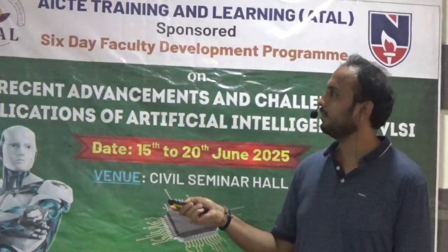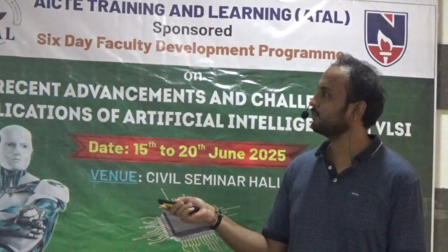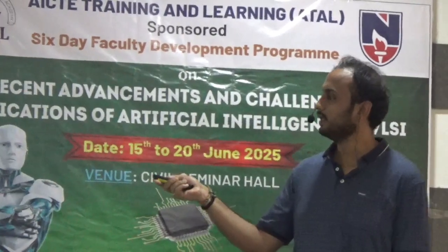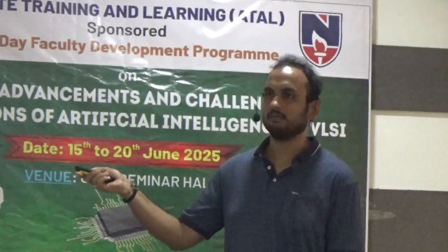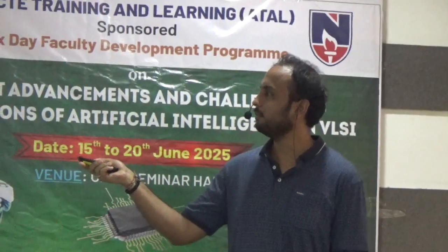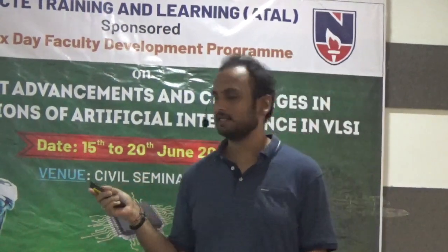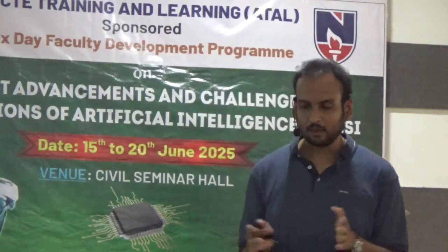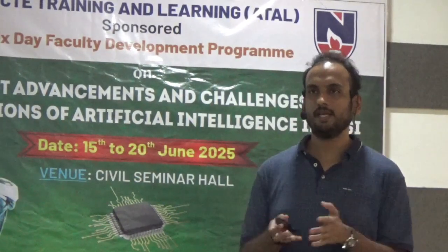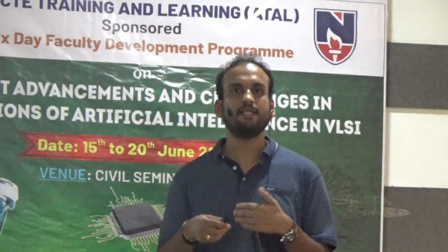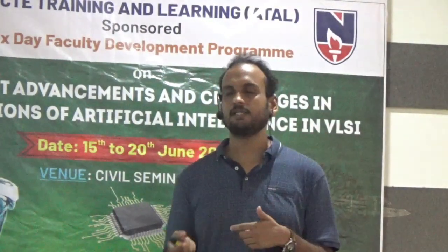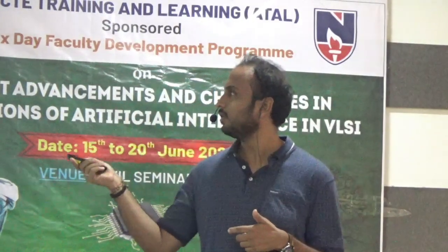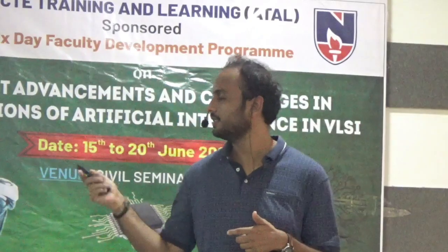And this is how we plot the FT and FT max. FT max will increase with scaling down the technology, but beyond a point it will again saturate. In 20 nanometer you may get the maximum peak FT max, but after that this FT max will saturate because of the parasitics in the design. If you narrow down the transistor, you will get lesser parasitics, but finally when you go for the routing, additional parasitics come into the picture, and that will degrade the overall FT max. So this is why it is degrading.